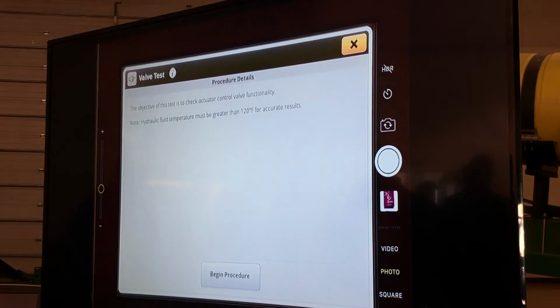Like I said, that's what I've experienced in the past, can happen. If that still fails, and since it has now failed two times, then we probably have a bad valve and need to replace it. So if we do have a bad valve, we can open that up, replace it, and once again, need an air purge. Anytime you introduce air into that system, we need to do an air purge on it. That way we don't get some jolty performance.